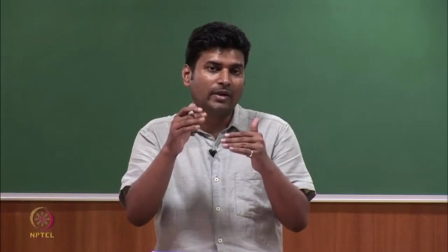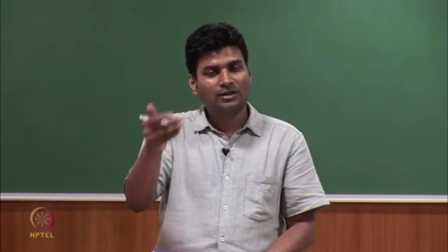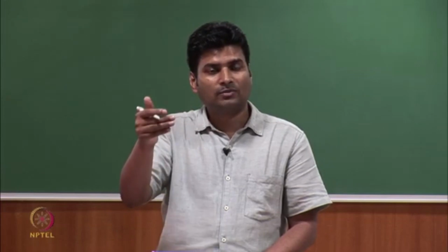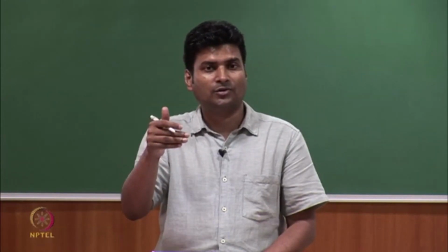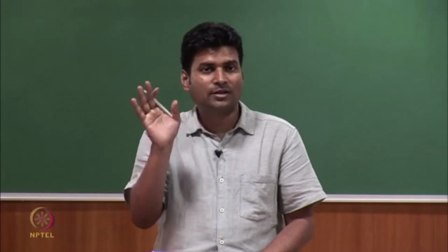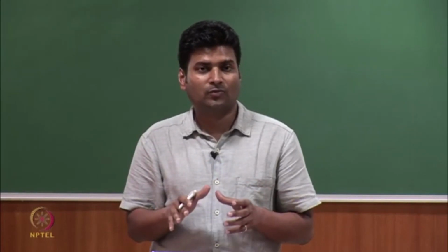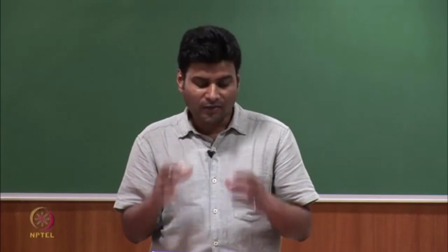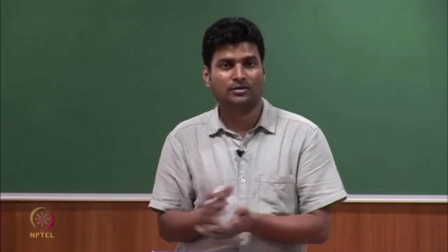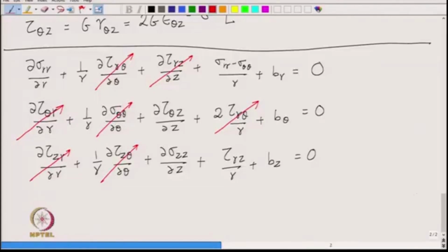We can't say that del sigma x x by del x is 0, or del sigma x x by del y is 0, or del sigma y y by del y is 0, or del sigma z z by del y is 0. So, because there is no theta, so there is no cancellation there. So, that is the advantage of using cylindrical coordinate system. Whenever you have axis symmetry, of course, the cylindrical coordinate system is a lot useful, because you see lot of cancellations. Okay.